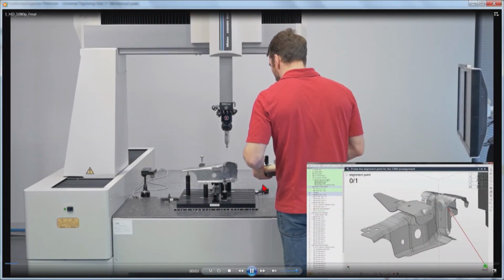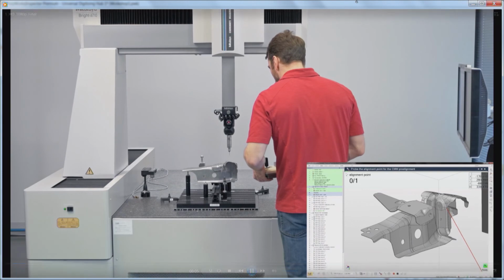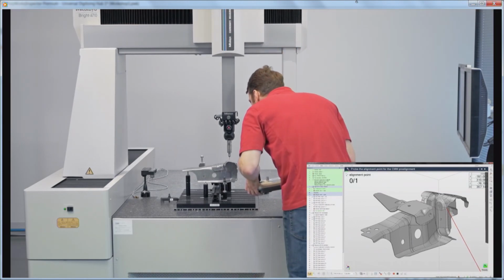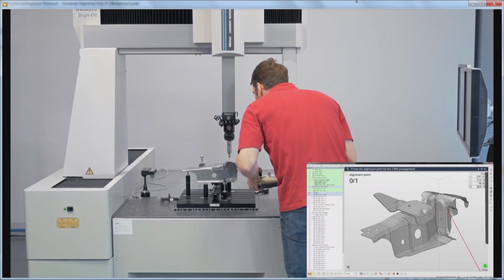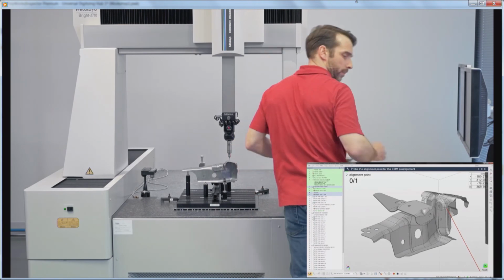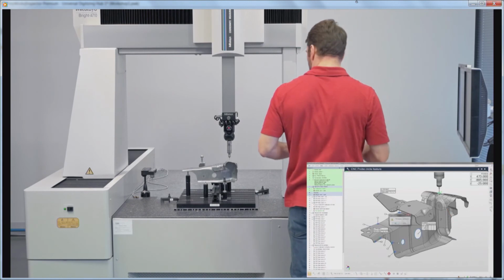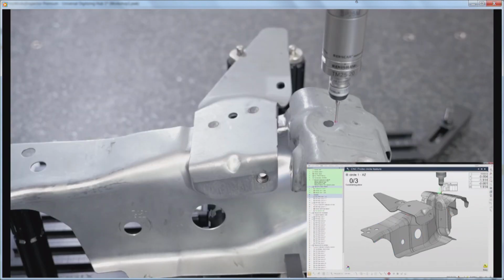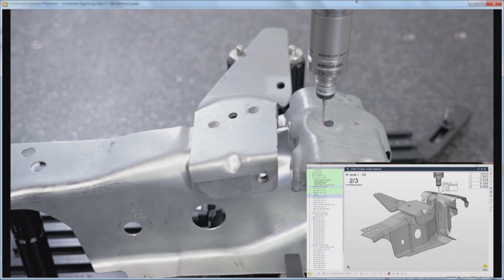So we can see here our operator performs the sequence by first bringing the CMM in the middle of our first circle to perform the CMM pre-alignment. Now, once the point is acquired, this is where the sequence will start measuring using the CNC probe method. And we start by measuring the first constraining plane for our four-way circle, followed by all the points inside.